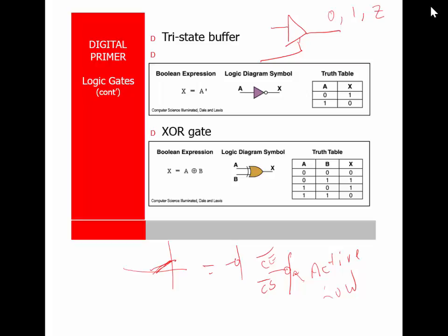because if we look at a carry, for example, if we want to add a single bit, a half adder: 0 plus 0 is equal to 0, right? 1 plus 0 is equal to 1. 0 plus 1 is equal to 1, right? 1 plus 1 is equal to 0 with a carry out.